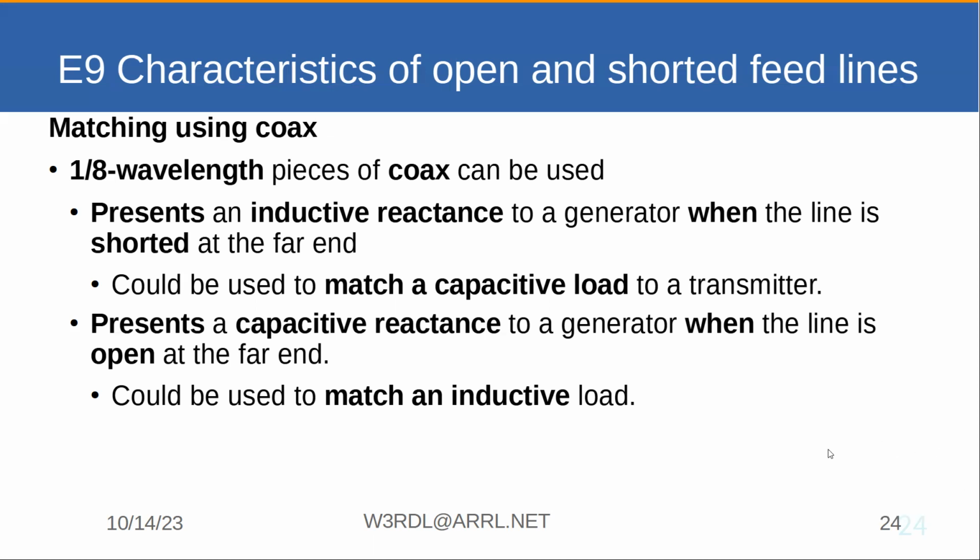I guess you're saying, depending upon how much capacitance or inductance you need, you can do a quarter or an eighth wavelength. Yeah, I guess it gets you close. One of them might be closer than the other, but you want to use something that's harmonically related. But I could do a hairpin with a sliding short and get there too. Billion ways to do it.